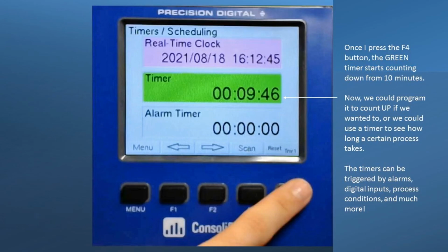and to be able to see how long it takes to fix a problem, right? And so what we can do with that is we can actually have that alarm timer. We can have that go to a bigger alarm that's in the plant. We could have that send a signal to the control room, letting them know that the alarm is still active. Or we can actually data log those alarm timers.